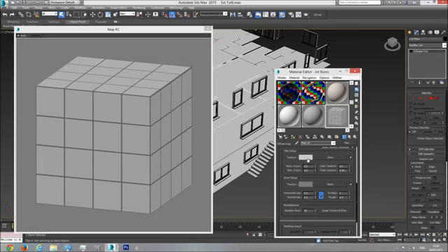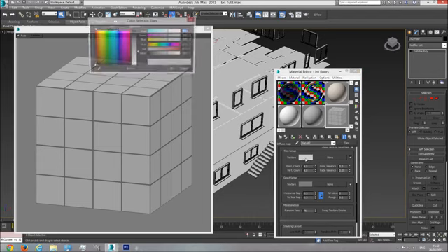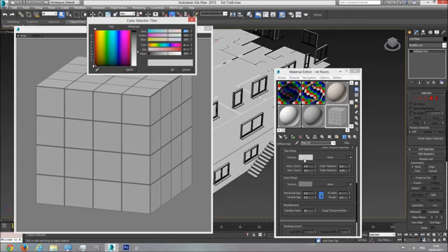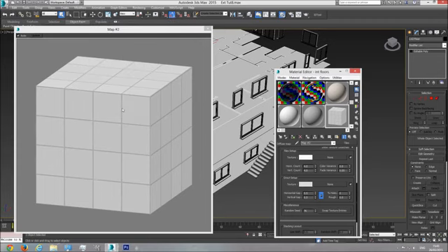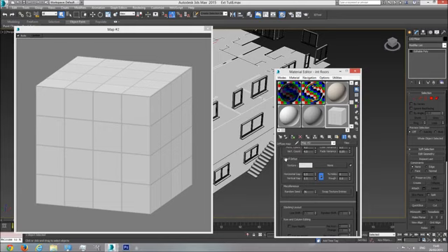So now I want to give this tile a color that is much brighter than this one. It's going to be almost white, 240 for the tiles. And the separation between tiles is going to be also brighter, something like this. I'm going to make it much thinner. So let's go down here. In the grout setup, I'm going to make the horizontal gap and vertical gap smaller. So 0.1, like this. Good.